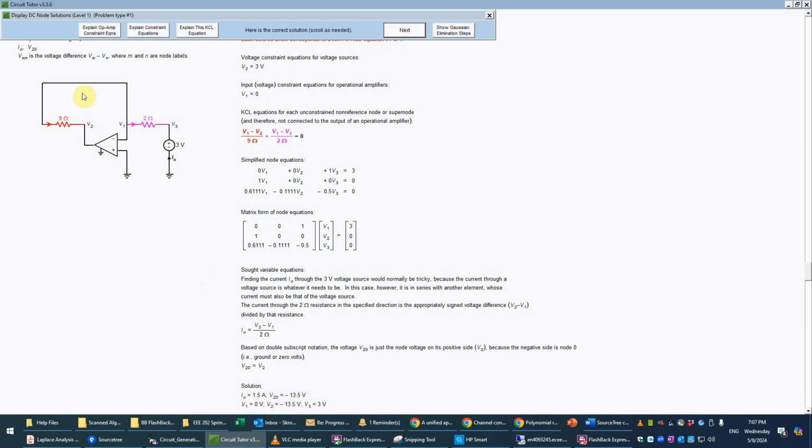And in this case, that current would be 1.5 amperes. So that would be current flowing basically from the 3 volt source to what's effectively a ground here. V1, remember, is effectively a ground because it's 0 through the 2 ohm resistor. So it's just, again, from this formula.